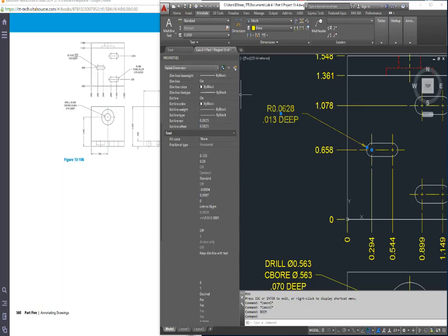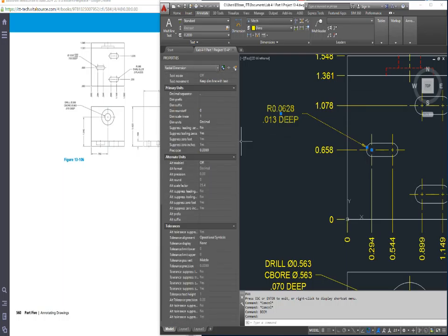Everything in the dimension style is listed here. So I need to add tolerance in there. That's going to be tolerances, display a tolerance, symmetrical, nope, there we go. And then it gives me an upper limit. And I'll say 0, I think that says 5.